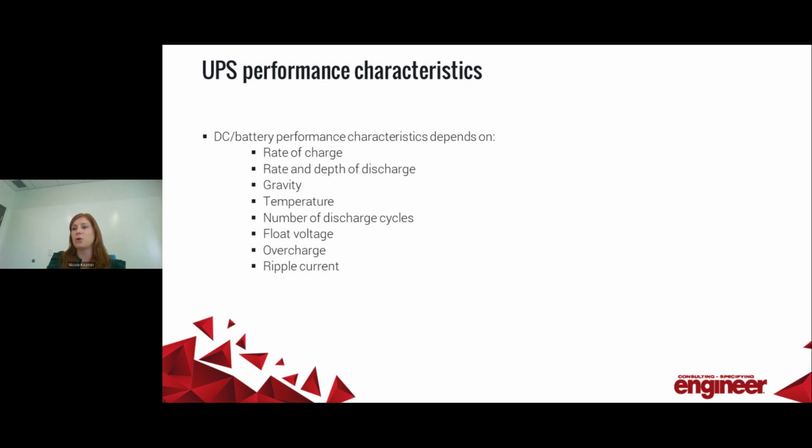Lithium-ion are gaining more popularity, I would say, because they have less cost over the life of their battery. The lifespan is about 10 to 12 years. They're much lighter and smaller even than VRLA, with less maintenance. They can operate at higher temperatures and have a faster recharge time, but they're much more expensive. This could be changing, but they're about 100% more than VRLA. And there are some restrictions on shipping methods. There's a higher risk of thermal runaway.